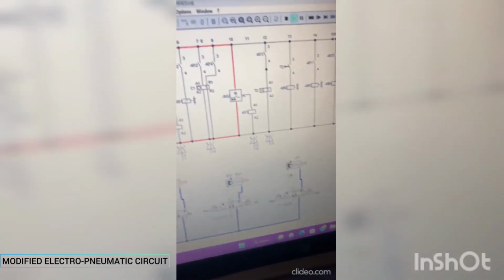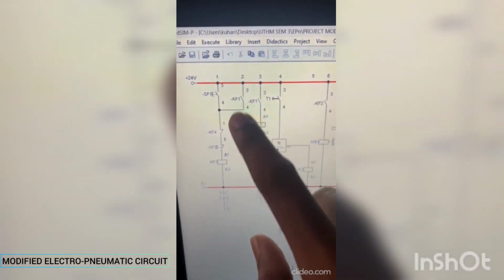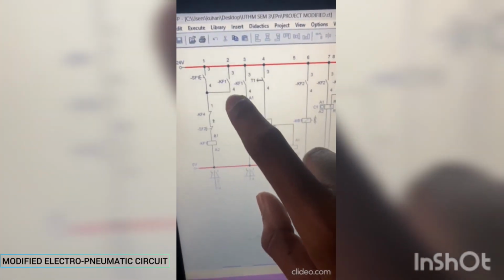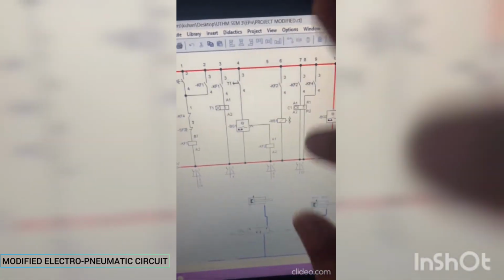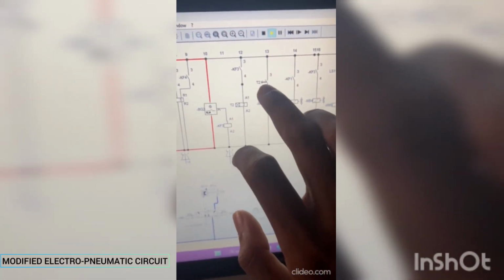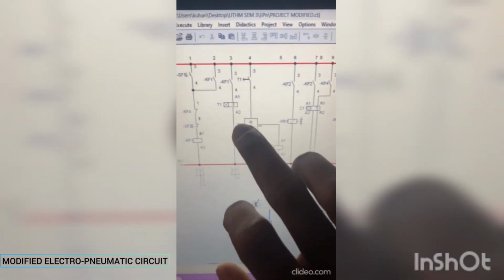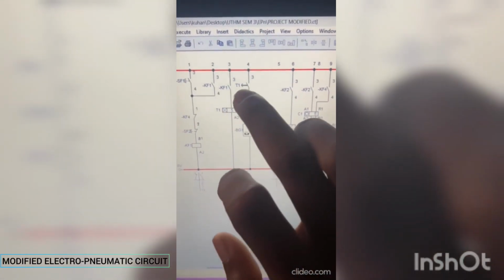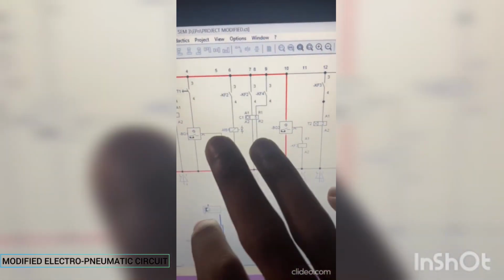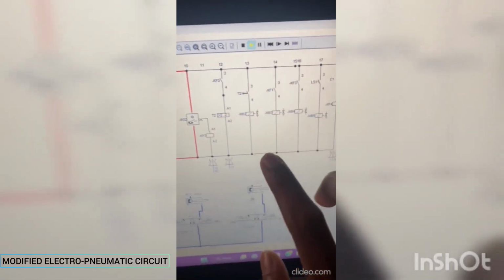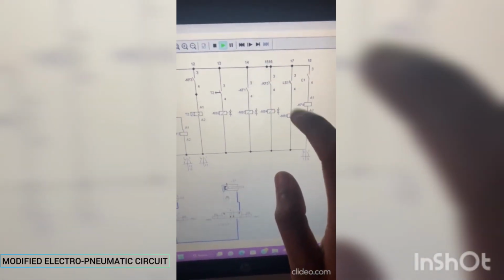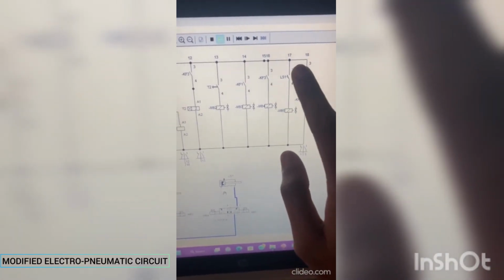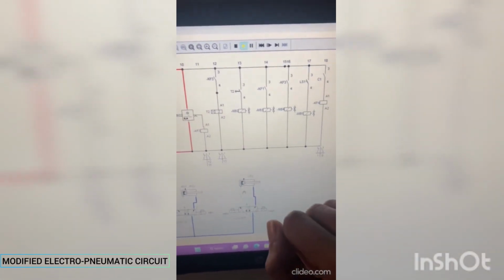Okay, so I have also made some modifications, which is placing the latching, and also this timer contact relay. So here there's another one, a timer contact relay for this timer. Solenoid number as usual, and then I have also added in this, as usual, limit switch 1. Like I said, this will open, so it will not give power supply to this solenoid valve, to make this thing retract back.